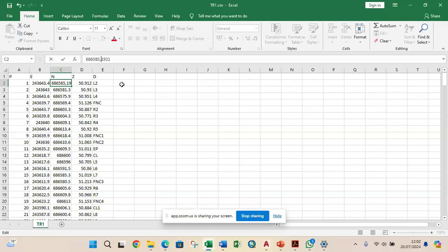That particular comma will disrupt you from importing. You will struggle, wondering why am I having this error? Why am I having this error? But the software will give you a hint and take you up to that point where you have that error, that comma sign that he put instead of a dot. He made a typographical error. Instead of putting a dot, he put a comma sign in one of the data, one of any of these points that has this dot sign. That does disrupt your work.